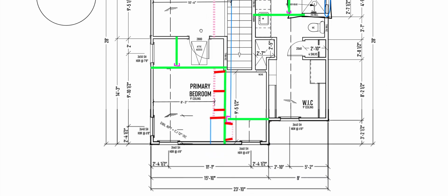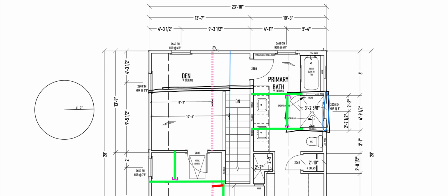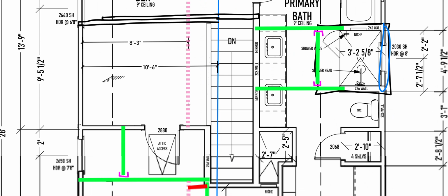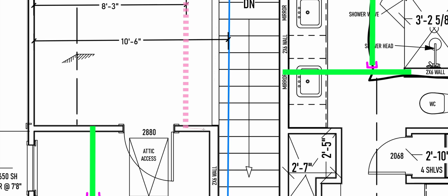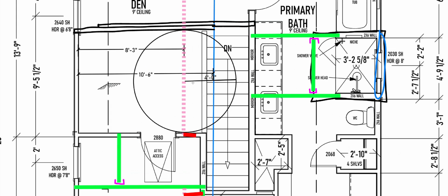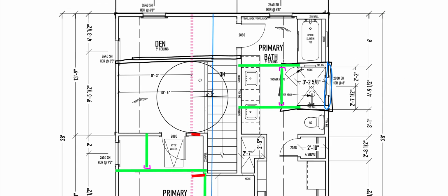So that's my brace. My purlin is going to be along that line. So now I need to brace that. This end could be just set on the wall, nothing crazy there. And then I'm going to take my 4-foot rule, come in here, and add a brace. Okay, so this is a railing. This is not a wall. So I need to think about something here.